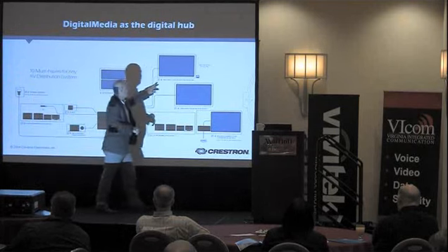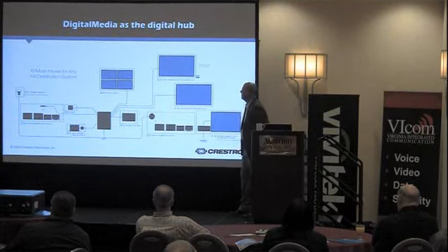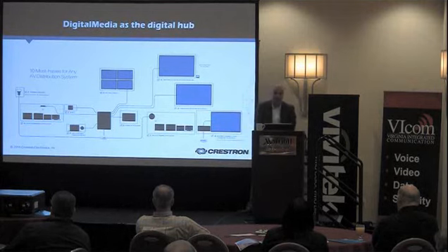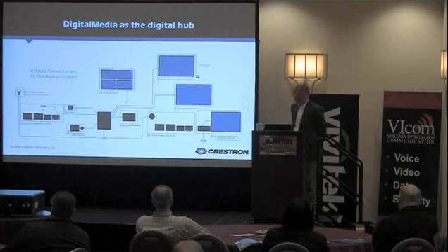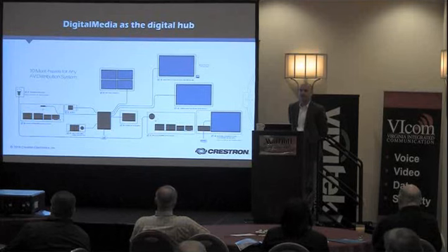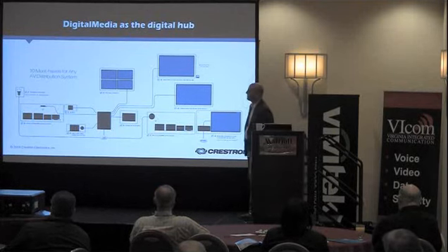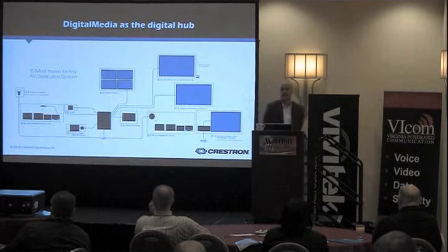Direct point-to-point for 4K over twisted pair. Downscaling, as we talked about, is very important for taking 4K content and pushing it out to existing owner-furnished equipment. And then finally, streaming to any other locations worldwide that have a digital media switch. This is exactly what's different from the traditional matrix switchers we've seen in the past.